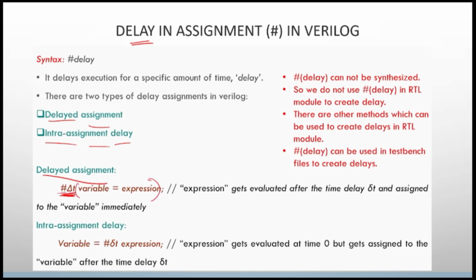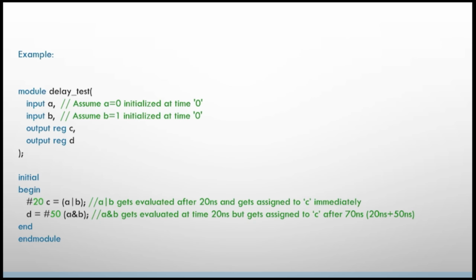When it comes to intra-assignment delay, the delay is within the expression, which means before assigning, you give the delay. But in delayed assignment, after assigning the value to the variable, you give the delay. So this is about the delayed assignment and intra-assignment delay.